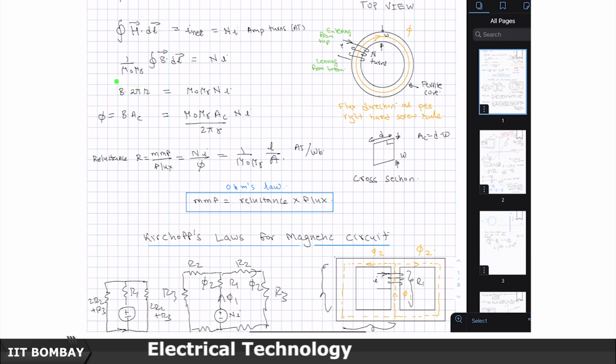Iron is not a linear material, but B divided by mu 0 mu r, B dl will become n times I, and the direction of B and direction of H are same, because B equals mu 0 mu r H. Mu 0 is a positive scalar, and mu r is a positive scalar for ferrite materials. Now in this particular case, if I take a middle line and close it, that is a mean path, and I can use it for this magnetic circuit.